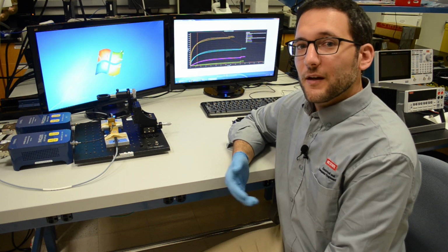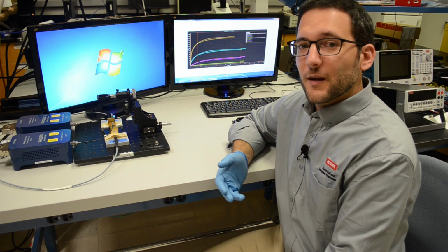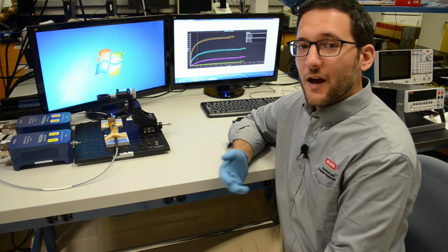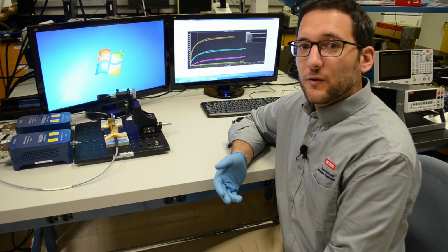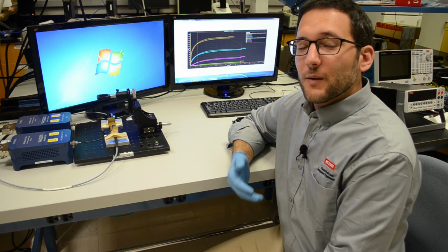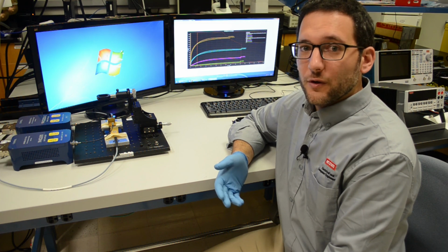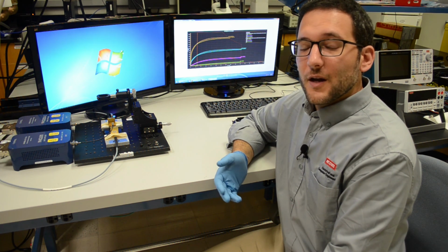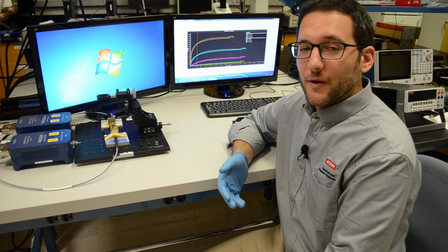Then we explained that further modifications to the test setup can be made in order to test at even higher voltages. Number one, we can use a high voltage power supply. And number two, we can introduce something like Fluorinert to ensure that we don't break down the air before we break down the device itself for the measurement.